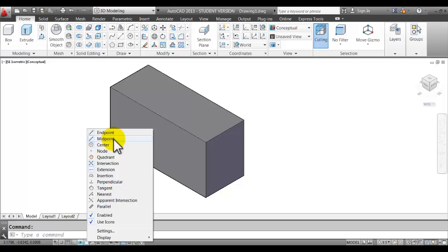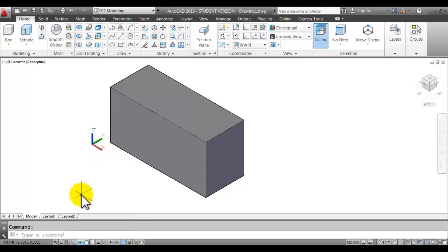I'll go ahead and use my escape key to get this menu out of here. And make sure that that 6th icon is actually blue so that you kept it on there at the bottom left. Also, the other icon that we're going to be working with is called Allow Disallow Dynamic UCS. It looks like a little L shape with a yellow lightning bolt. And what that does is it allows us to draw on this face of the cube.